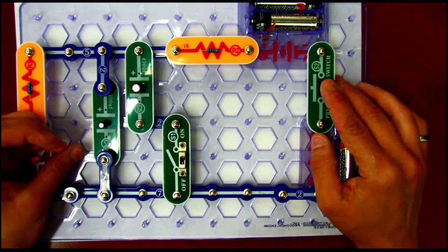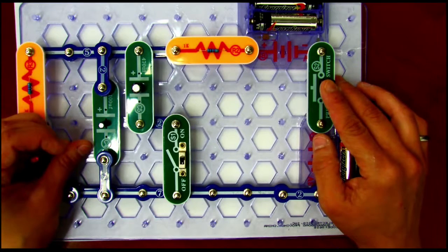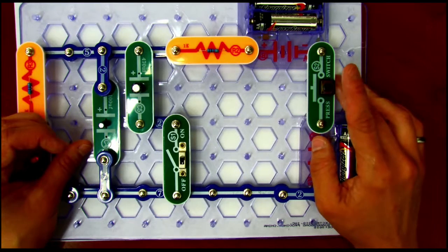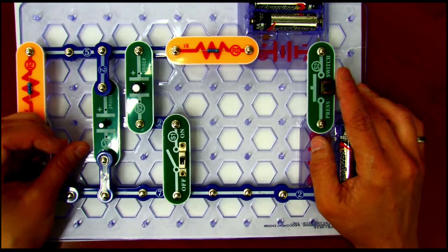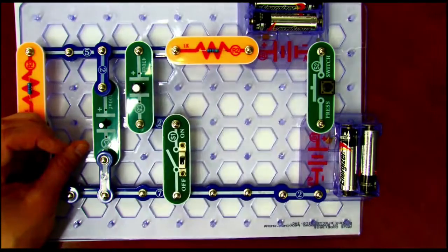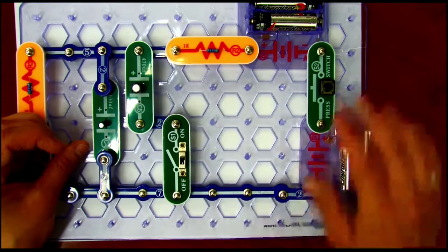So he's lit up. If I unclick the switch, I'm going to use the energy then from the capacitors. You see it takes a little while longer, actually quite a bit while longer, for the light to completely go out because we've added a big fat 470 microfarad capacitor in there.